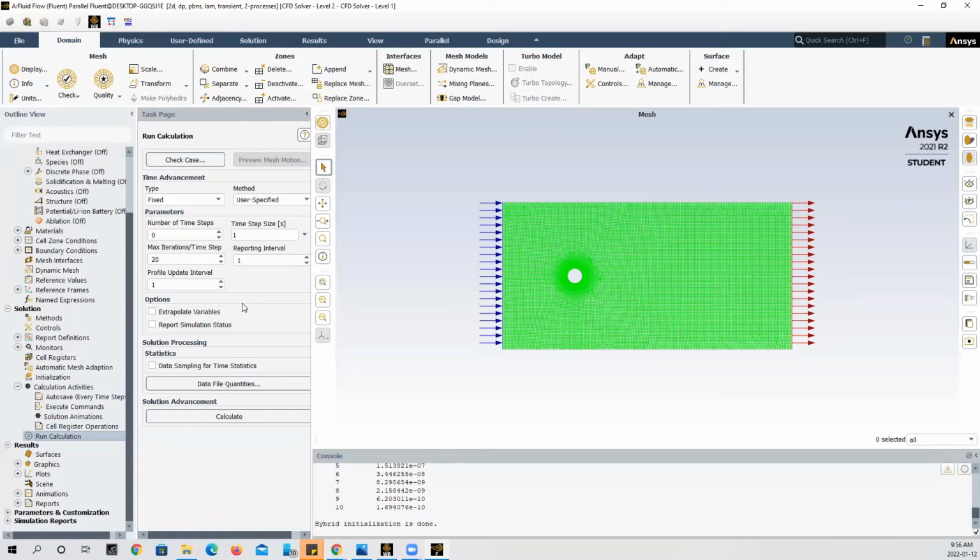So for the simulation, I'm going to put the size of my time step to be 250 seconds. And we're going to run this for 4,000 time steps. And the reason why this number is so large is because we want to see the full transient time of the von Karman effect. During the calculations, we're going to see the lift and drag plots.